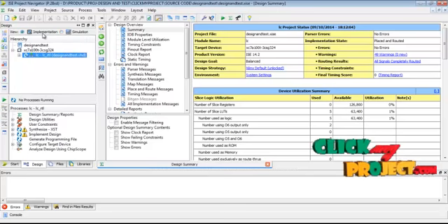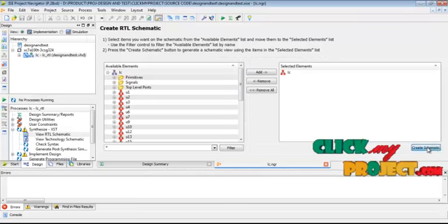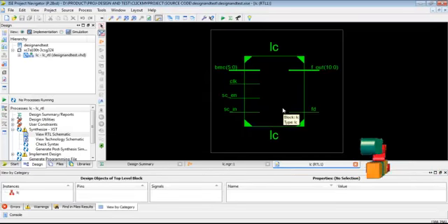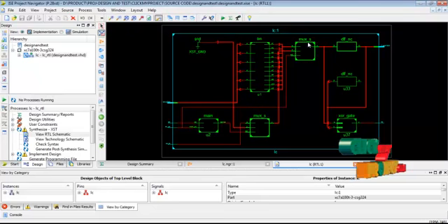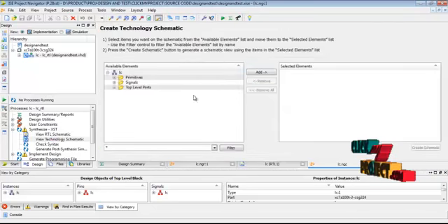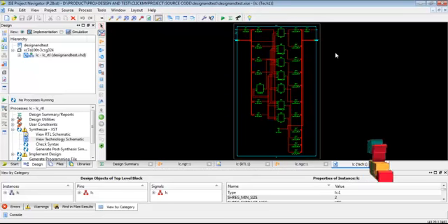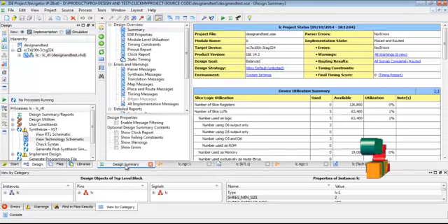Then we calculate the implementation process, then create the view RTL schematic. This is our LOC and LOS based testing architecture. We developed the benchmark circuit and the overall combinations in the RTL diagram. The RTL diagram represents the logical blocks placed in our testing architecture. Then we go to the technology diagram, which represents the lookup table and flip-flop pairs, and the input output connections placed in our testing architecture. Then go to the design summary process.